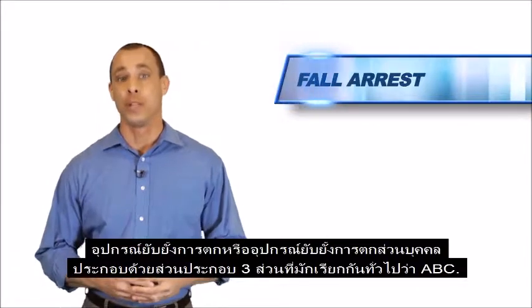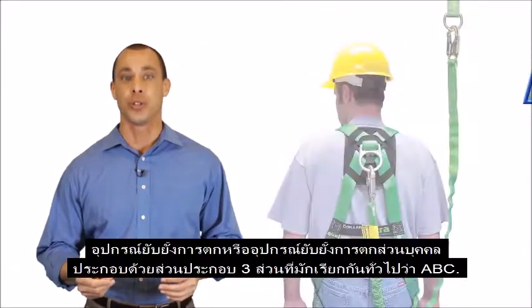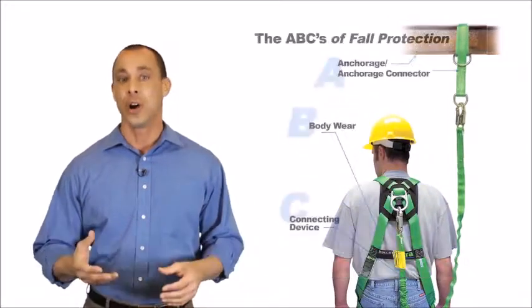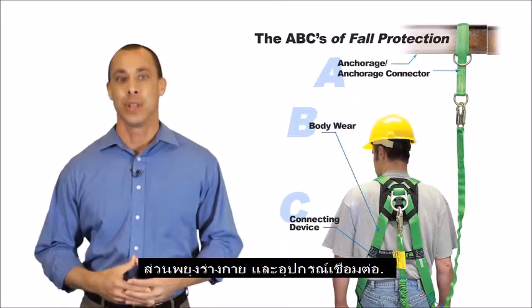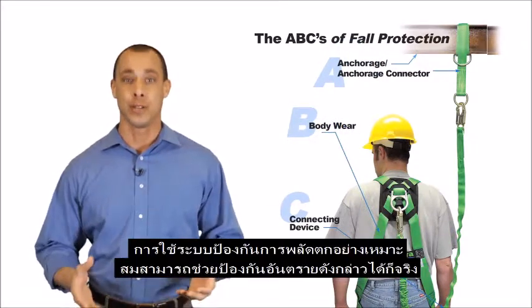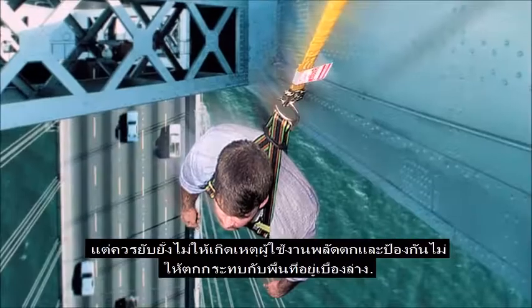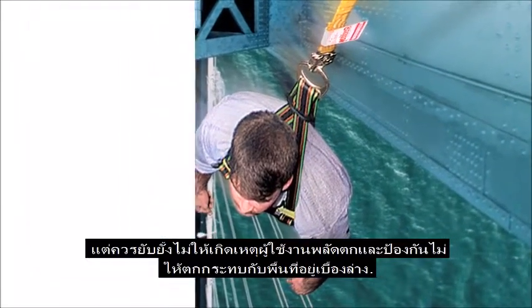Fall arrest equipment or personal fall arrest systems is comprised of three components that are often referred to as the ABCs of fall protection. These are anchorage connector, body wear, and connecting device. Used properly, a fall arrest system does not prevent a fall, but rather suspends a worker in the event of a fall and prevents impact with a lower obstruction or the ground.